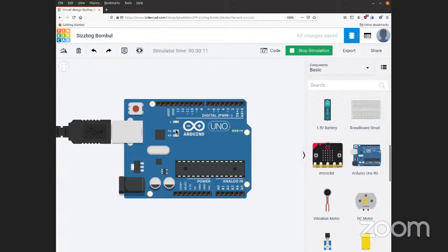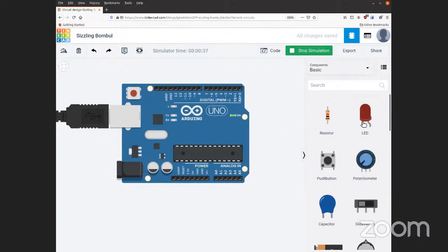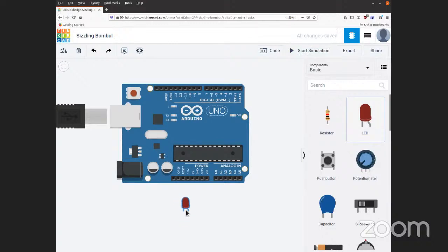Now, just having an Arduino is pretty boring, and your Elegoo cars are a lot more than just an Arduino board. So let's have a little fun by adding some more components to the design. Let's start off simple and just add an LED. First we have to scroll our components bar back to the top. Once you're there, you can drag the LED onto the interface below, and make sure to put it below the Arduino. Now, you'll notice that this LED is oriented the wrong way around.